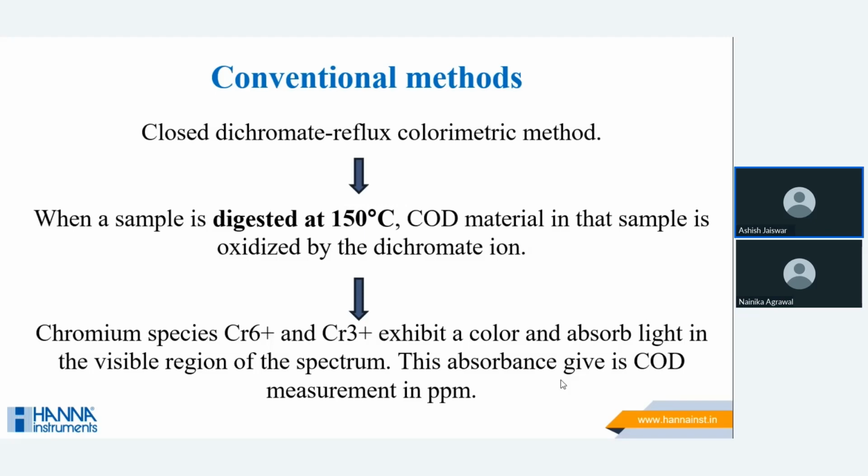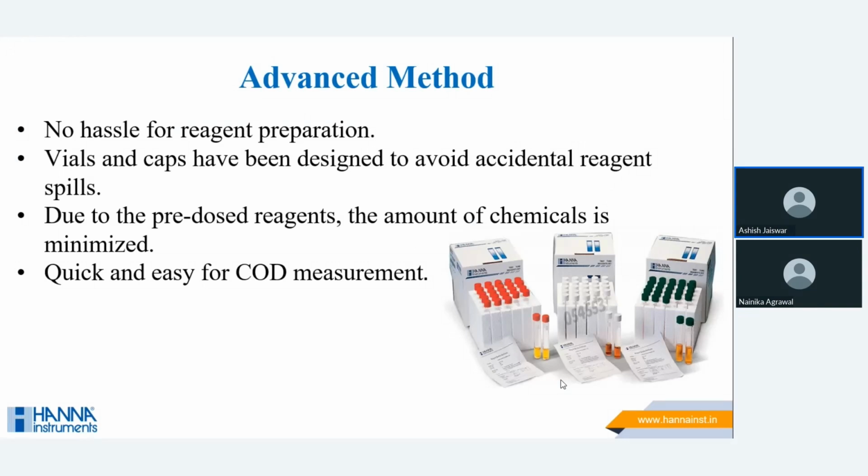The COD test is often used to monitor water treatment plant efficiency. The test is based on a strong oxidizing agent under acidic conditions, which can fully oxidize any organic compound to carbon dioxide. And we are providing advanced methods such as the colorimeter HI 83399.